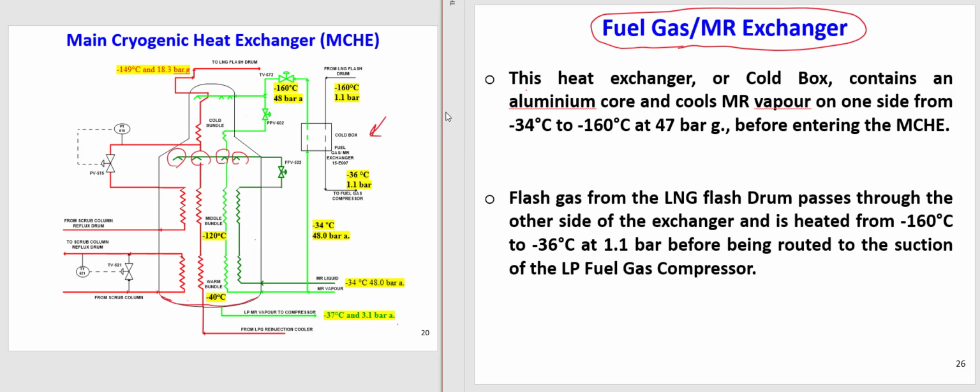This cold box has an aluminum core and cools mixed refrigeration vapor on one side from minus 37 to minus 160 at 47 bars.